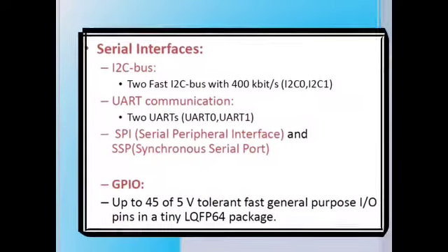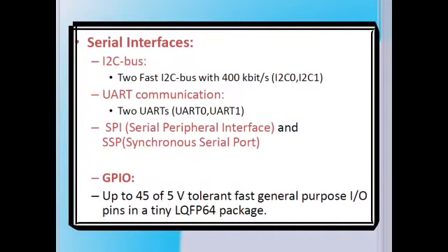It has serial bus interfaces: 2 fast I2C buses with 400 kilobits per second, 2 UARTs, UART0 and UART1, and 1 serial peripheral interface and synchronous serial ports.